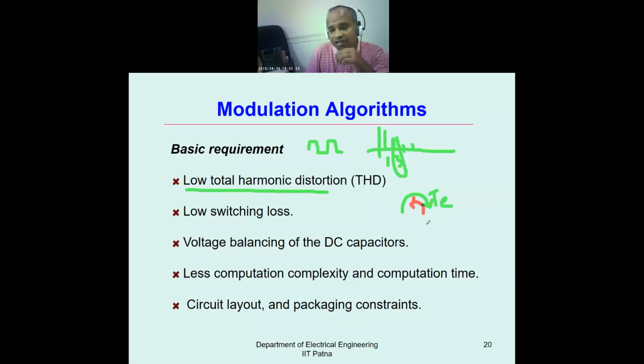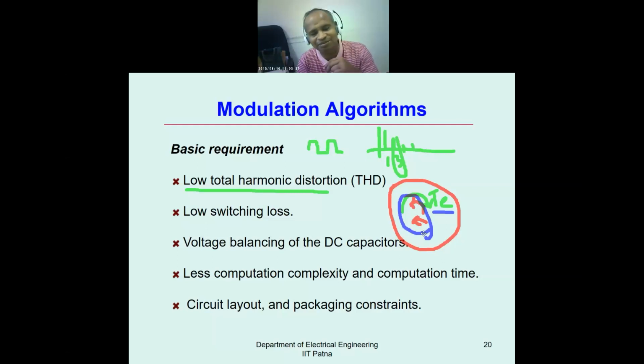The sixth again is in a similar direction. So the net torque generated by the induction motor is the torque developed by the fundamental minus the torque developed by this harmonic component, so the net torque becomes lower.